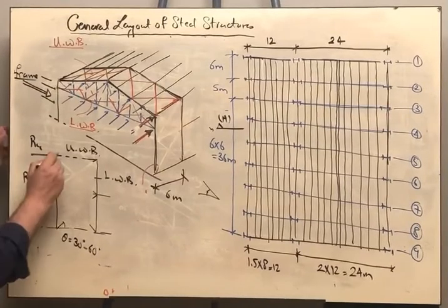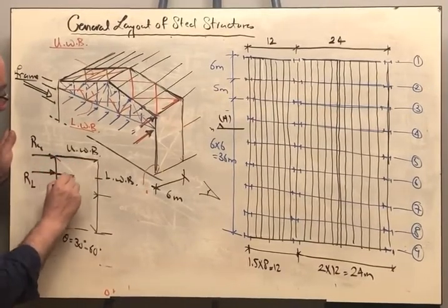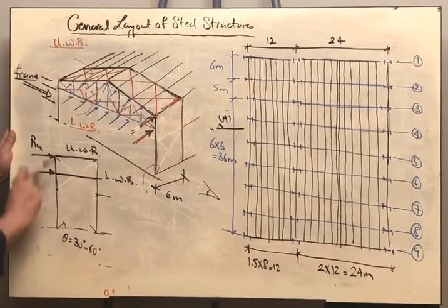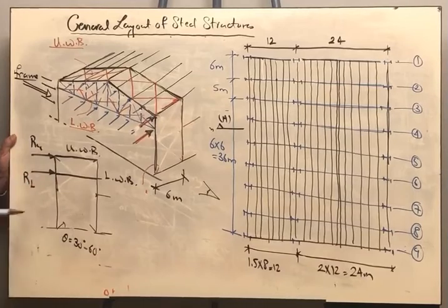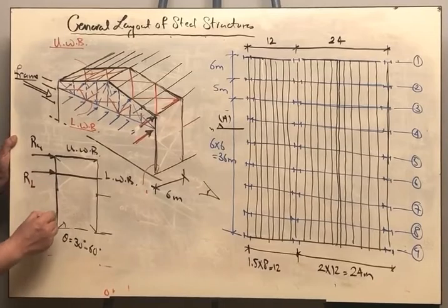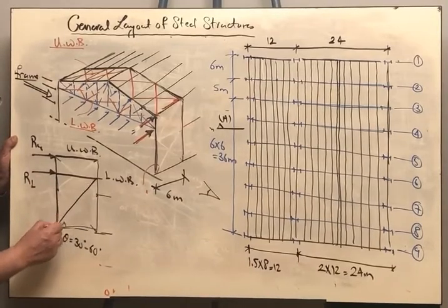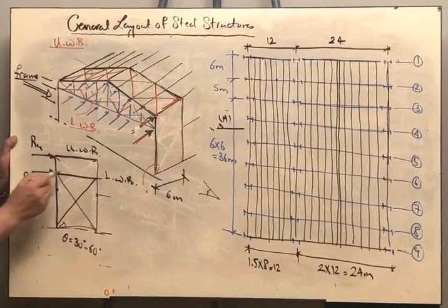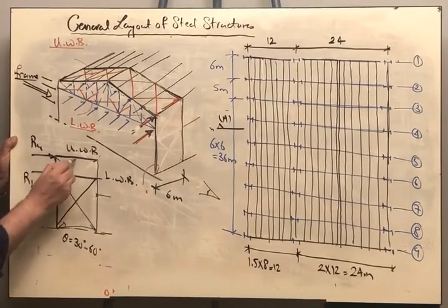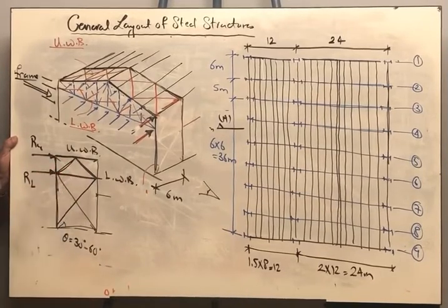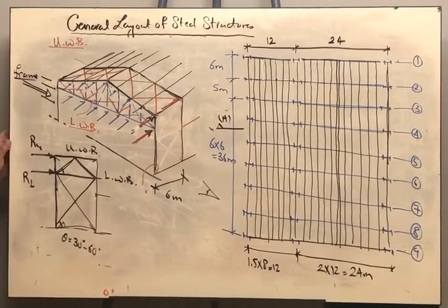And I will have to have a member here and another member there. Now I want to establish the shape of the transversal bracing such that the angle is between 30 and 60 degrees. So I will see here the relation between this length and this length. Maybe I can take it in one cross like this, but this length is so narrow compared to the 6 meters or the spacing. So instead of having a cross like that, we can have a K truss. In this case, this angle and this angle range from 30 to 60.